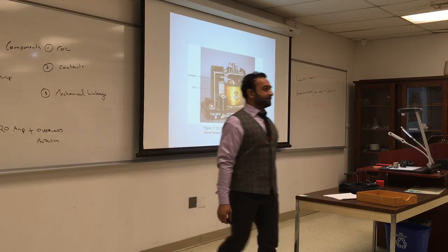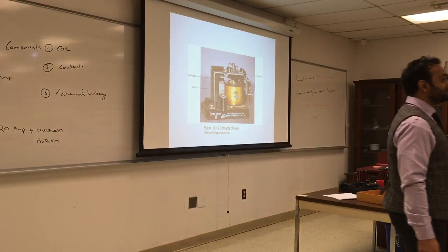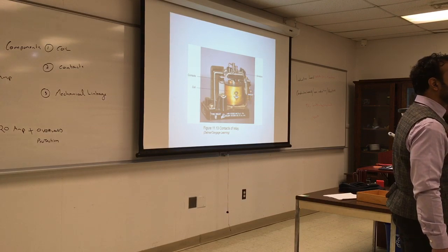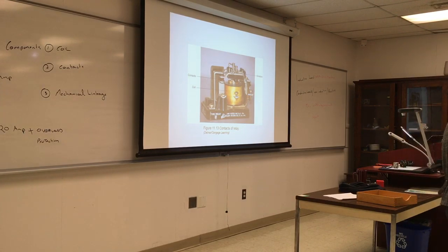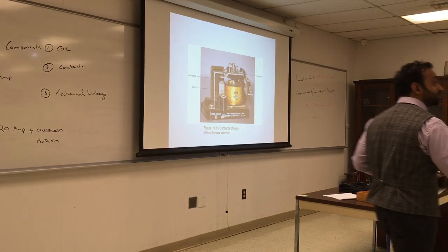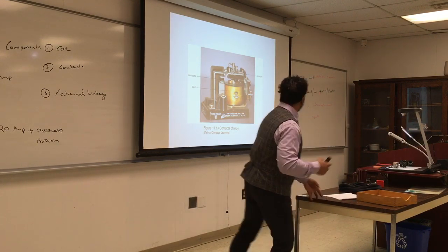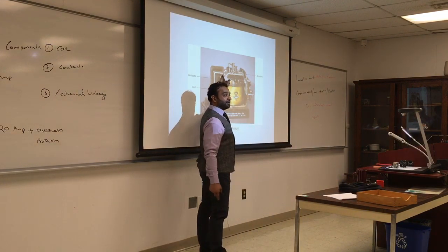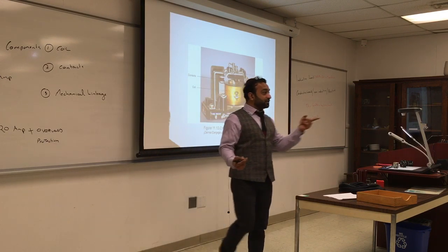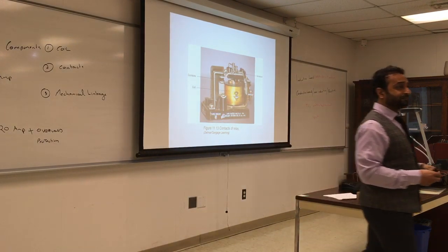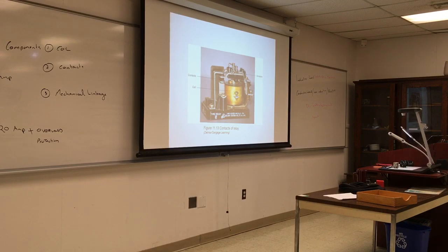How do you test that the contacts are actually connected? You can measure it, right? What else? You can also just measure the connectivity. There are two ways. First, you can check continuity between this part and this part, but you don't know how much goes through it. So measuring voltage is really good. Measure the voltage before and the voltage after. Are you getting the same thing or not?